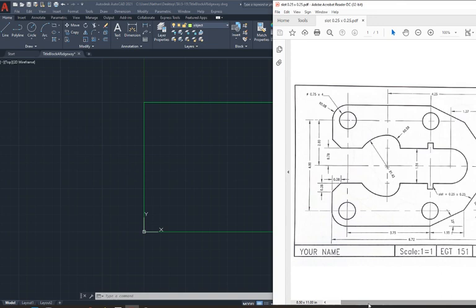So, generally when you're starting a drawing, you want to look for one of two things. The first thing you always want to look for is coordinates, because if there are coordinates, that's where you want to start. Now looking over this drawing, I do not see any coordinates. This means that as long as the drawing is within the bounds of our title block, then that's fine. It doesn't have to start at a specific coordinate. So if you don't have a coordinate, where do you start?